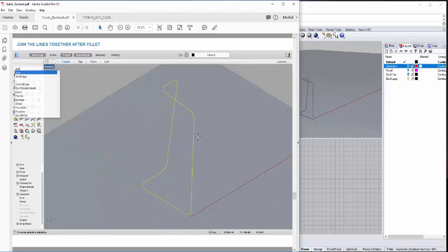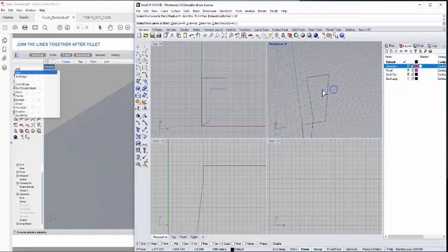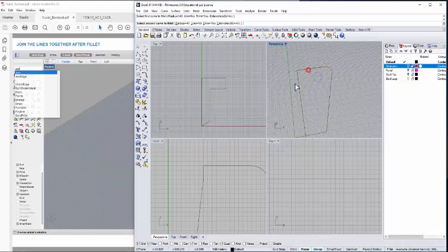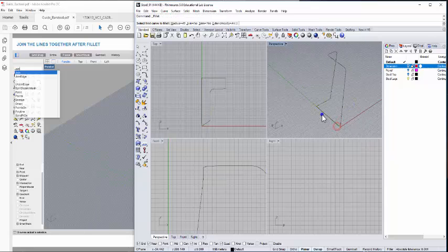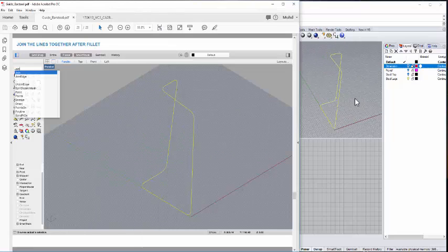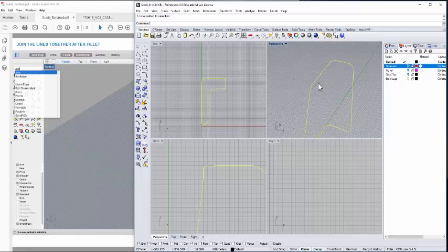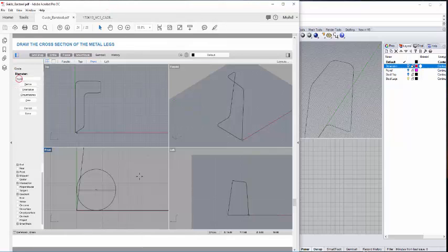So you can see it's quite nice and smooth here. Select first curve to fillet. Let me just change to 40. Then after that you just need to keep on filleting. Re-enter again. Once that's done and you have a very smooth curve, double check anything wrong. Make sure you do not miss any single thing. Go down, let me just see here.